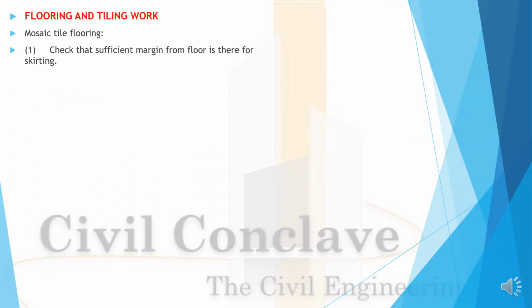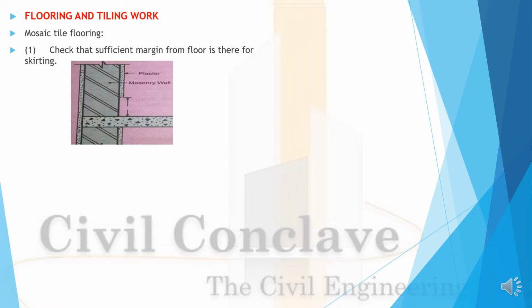Flooring and tiling work. Let us talk about mosaic tile flooring. Check that sufficient margin from the floor is there for a skirting. See, this is the methodology of how to do a skirting. Margins have to be ensured.